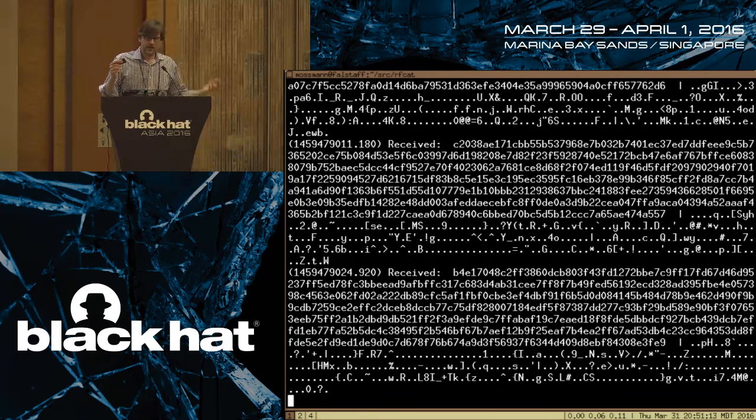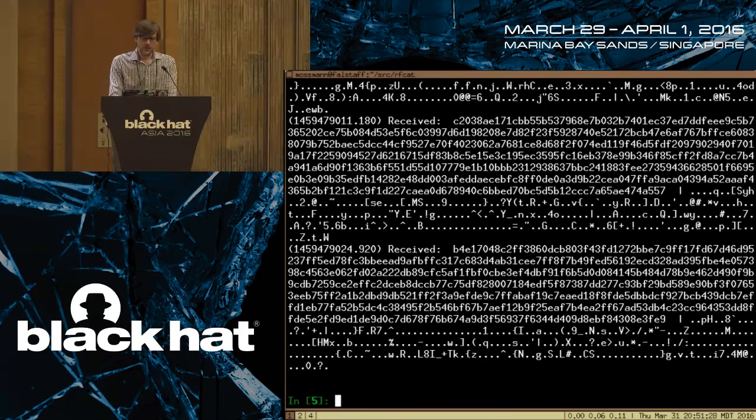I'm transmitting, and notice we're not seeing any packets received. We're not seeing anything other than this garbage that happened when it first started up. Let me transmit it again and see if it does anything. It doesn't do anything. The reason it's not doing anything, probably the main reason, is that there are two reasons. One is that it's expecting that a packet starts with a preamble. By default, the wireless transceiver chip that's on the Yardstick 1 expects to see a preamble of alternating symbols at the beginning of the packet.